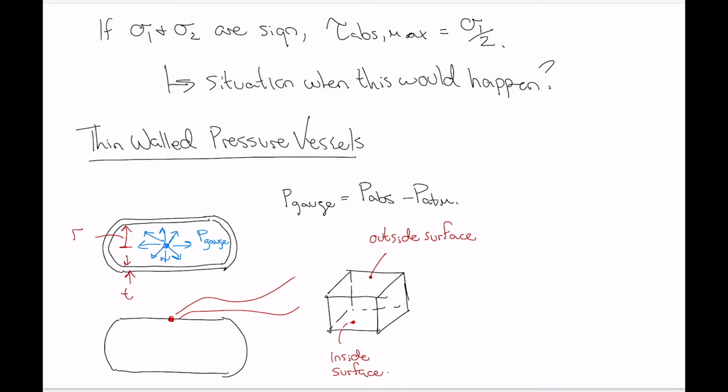Okay, we've got pressure within the tank, so we've got pressure pushing on both of the ends of the tank here, and that's acting to elongate the tank. So we're going to have a stress that's tensile and is in this direction here at point A. And that would be the same regardless of which point in the tank we chose. This stress we'll call the longitudinal stress, sigma subscript L.